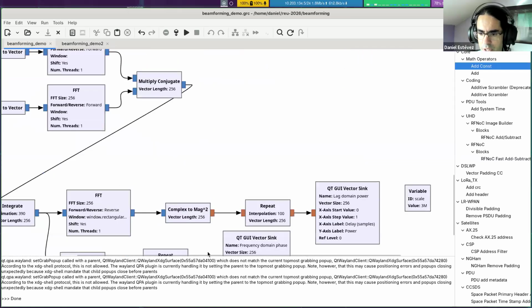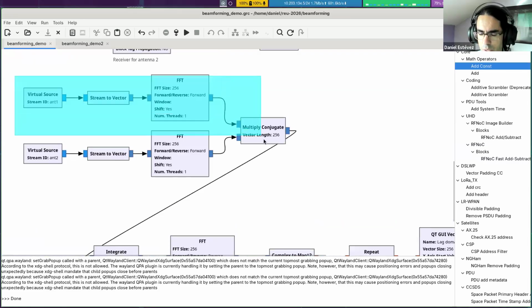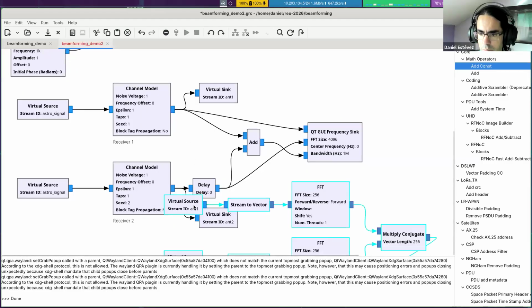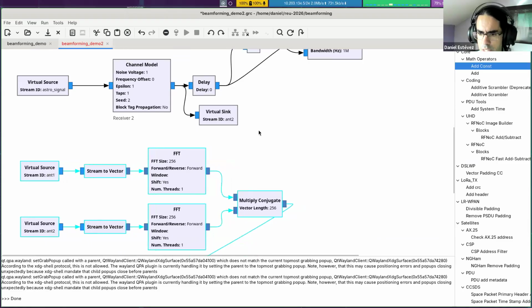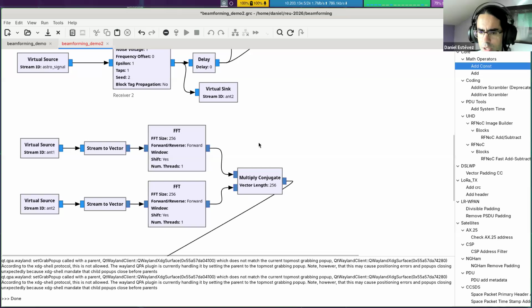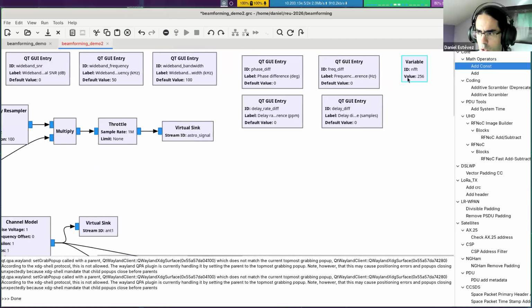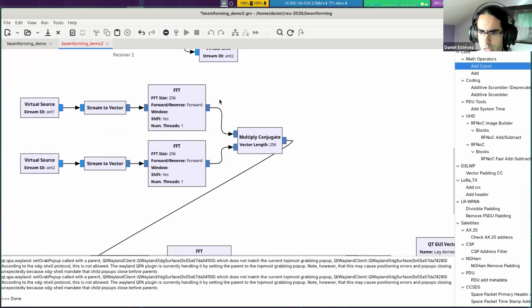And because there are a bunch of blocks, and this is quite similar to something we did last week, I'm going to copy all of this, and then I'm going to explain what this is. So this is all based in FFTs. It's essentially the same as the way I showed last week to calculate and plot the spectrum of a signal when we have a single receiver. But the only difference really is we have the two receivers. We are doing FFTs again. So remember, I copied an FFT size variable here. We are going to use 256. We don't need it to be any larger for this.